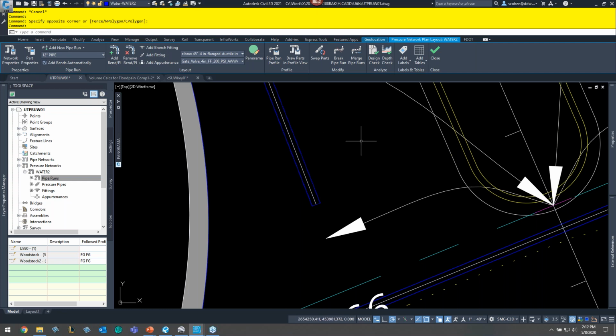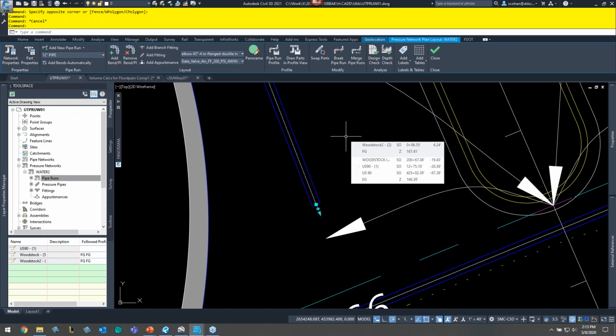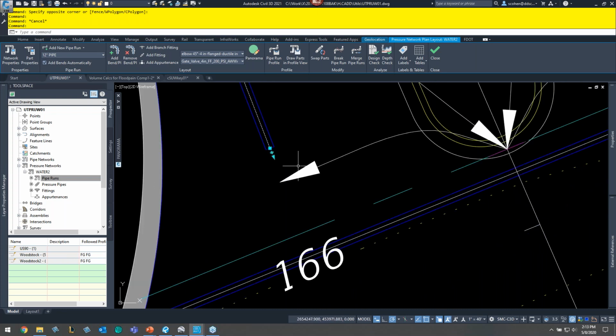And you can go to the pressure pipe properties, etc. Now in this case, I do want the alignment. I'll show you why. Because the alignment is what actually controls the way that this pressure network will get displayed. And this is, again, you want to make sure you maintain this connectivity. If it messes up, I have not yet found a way to reconnect it.